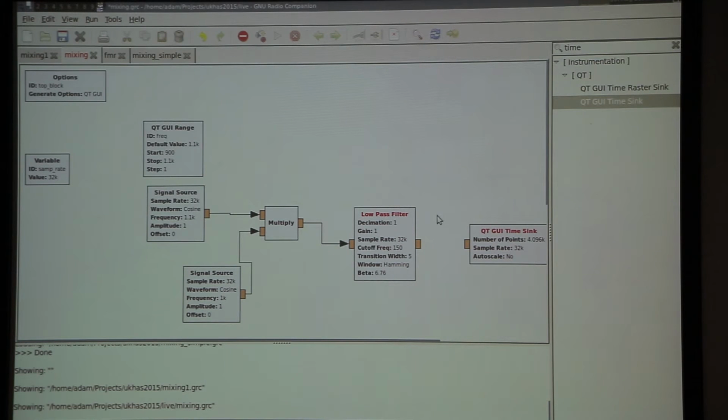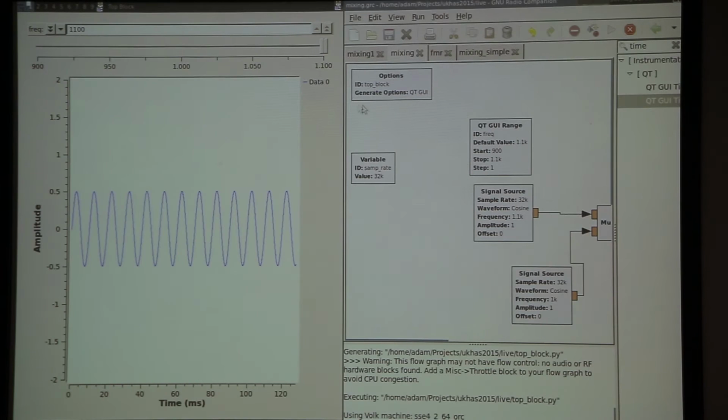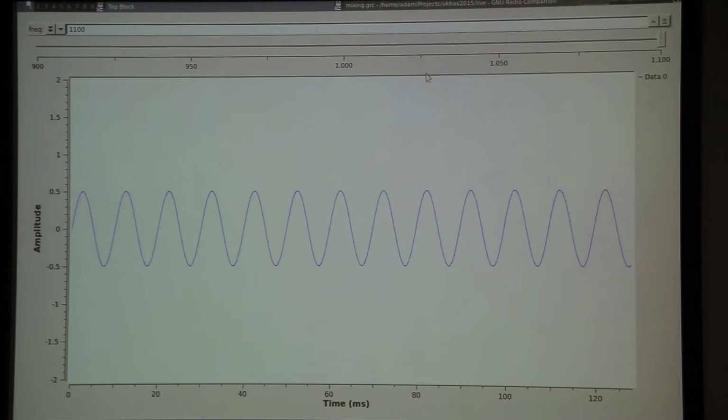The one downside to GNU Radio is there are a lot of these option fields, and sometimes it's a little mysterious what any of them do. But, okay, here we are. So we have a slider at the top that controls the frequency of a signal we're receiving, and we can see at the bottom the signal that comes out of our mixer. Right now this is representing 100 hertz, and it looks like it's doing about 10 cycles in about 1/10 of a second at the bottom there, so I could believe it.